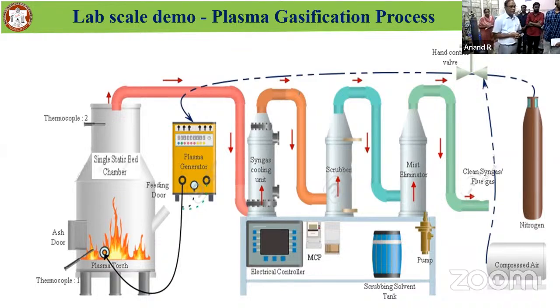We can go for either gasification mode or pyrolysis mode. In gasification mode, the given raw material is operated with 20 to 30% of the stoichiometric air-fuel ratio. We can control the equivalence ratio and operate between 0.3 to 0.4. So we call it the gasification mode.